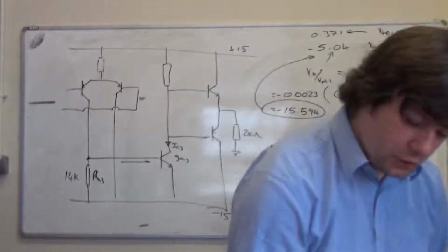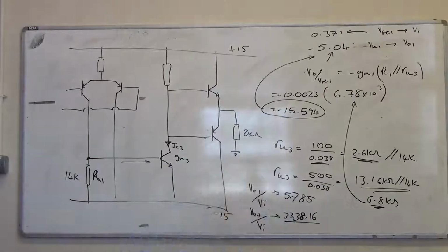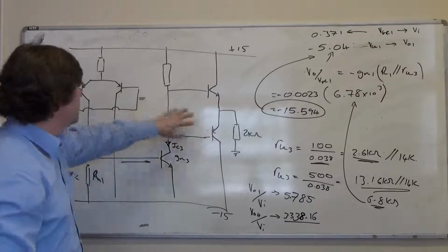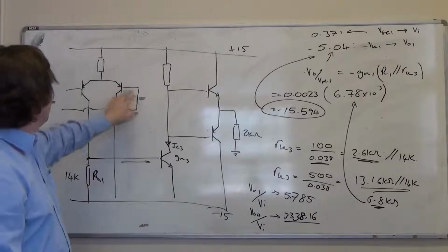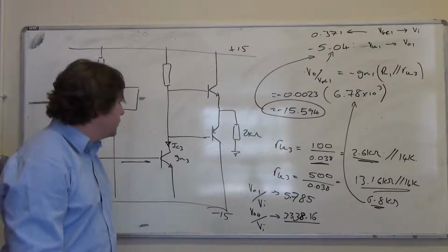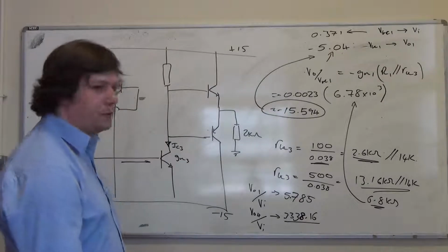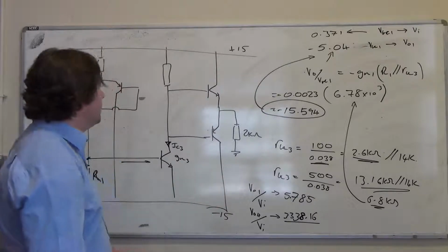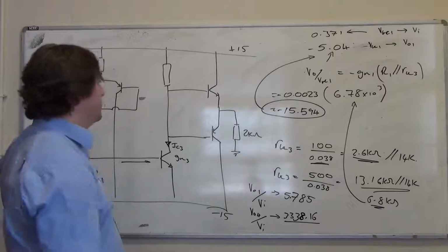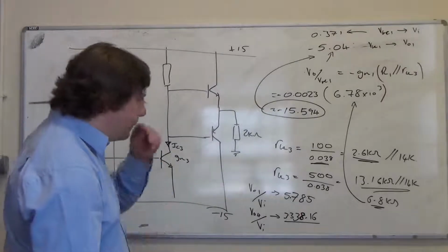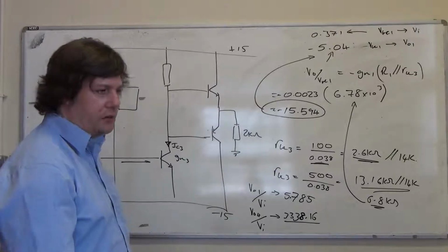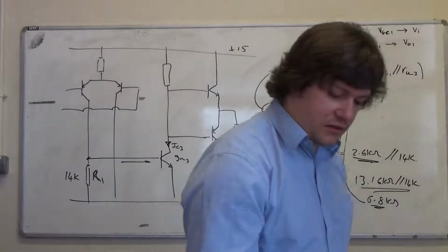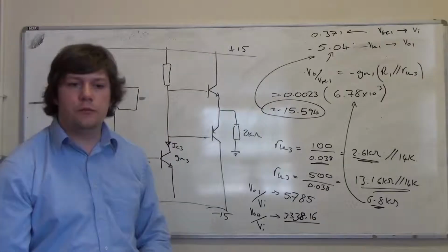And this of course is the open loop gain, and all that open loop gain that we've got, when we put some feedback around here, so we'll put some resistive network between the output and T2's base to set the closed loop gain as you would for a regular op-amp circuit, we will find that all this open loop gain goes towards reducing the distortion of the amplifier and increasing its input resistance and decreasing its output resistance and making it less sensitive to changes in component values and all the other good things that feedback does. So that's the key thing that changes when we change the beta.